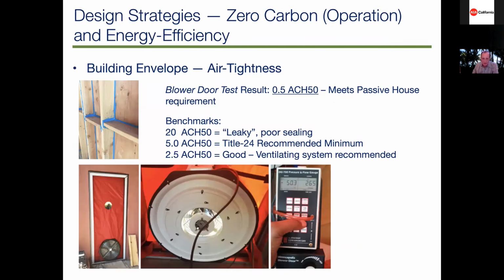And again, a blower door test, because it's a passive house, it's required, and you can see the photograph here, the kind of sealing he did between the studs and the wall. He did not have manufactured wall panels. Probably, thank goodness he didn't. It's stick framed like most construction, 2x6, but he sealed every single joint, and this was new to his contractor apparently, and took a little bit more time than they planned.